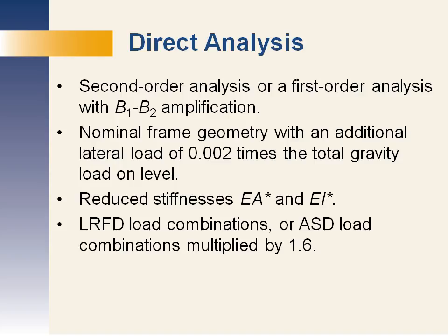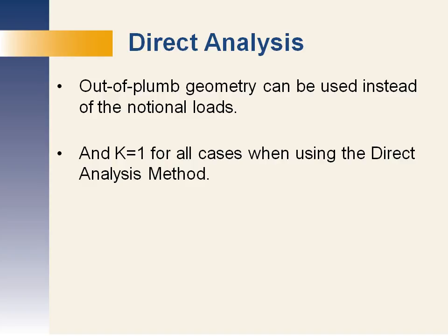And let me talk about one alternative. I said you have to put notional loads on. You don't actually have to put notional loads on. You can model the out-of-plumb geometry if you prefer. Now that's good for an existing building, not very practical for a new design that isn't built. You don't know where it's going to be. But if you know the actual geometry, you can model it.